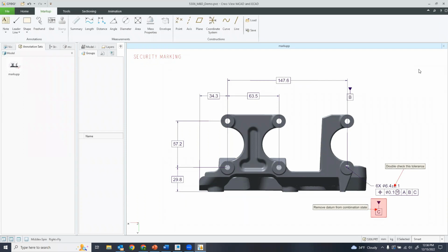Could you repeat that? I couldn't hear you there. Sorry, I think step files can't do flat to screen annotations. Well, we just had this issue where someone was exporting a product and it was showing every single annotation at the product level, especially the flat to screens were showing up in submodels. What's the recommended practice for product level step exports versus MBD part level step exports?